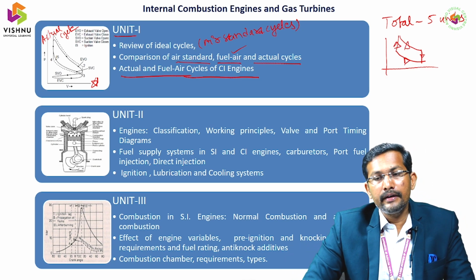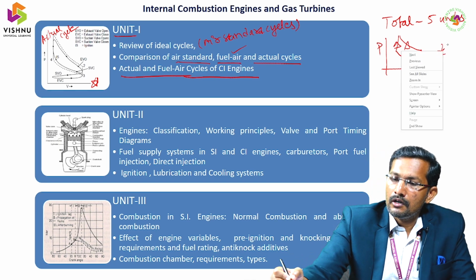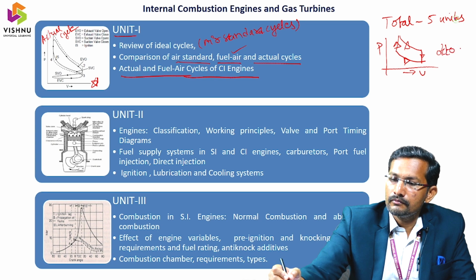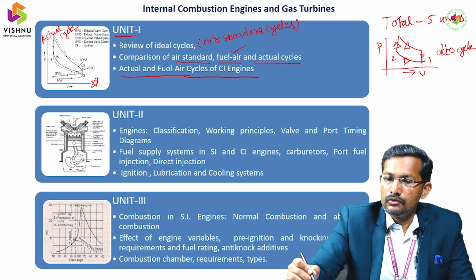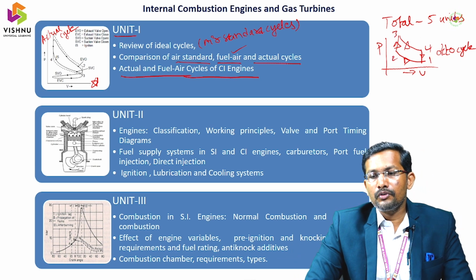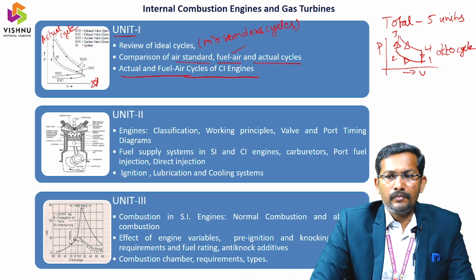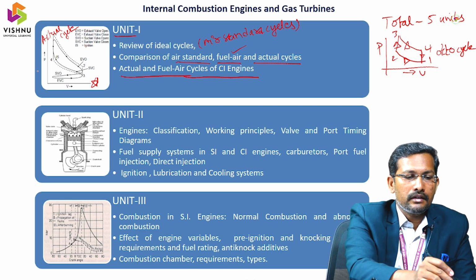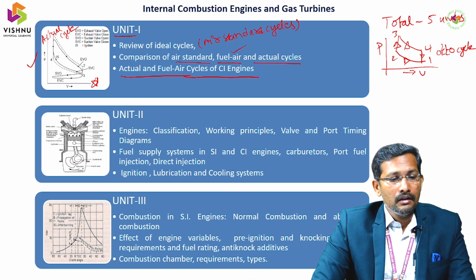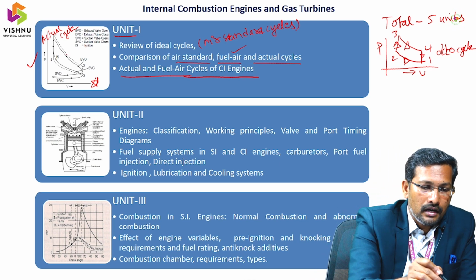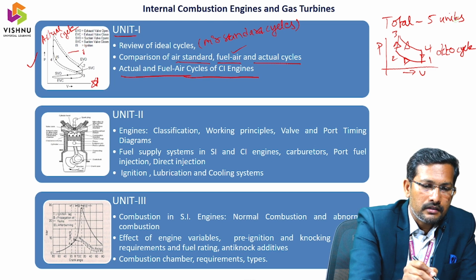It is like this. Ideal cycles, Otto cycles. This is P and this is V. This is the simple Otto cycle. In this Otto cycle, this is 1, this is 2, this is 3 and this is 4. Here, see, various curves are there, but in the ideal cycle sharp corners are there, because this is ideal, no losses associated. But in this diagram, various losses are there in actual conditions. So that is why there is a higher pressure, and that dashed line. See that dashed line. This dashed line is nothing but the ideal cycle.